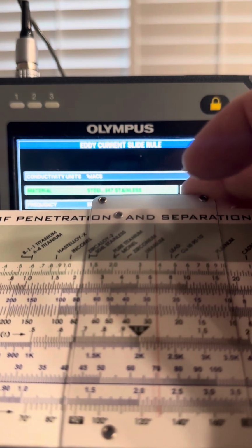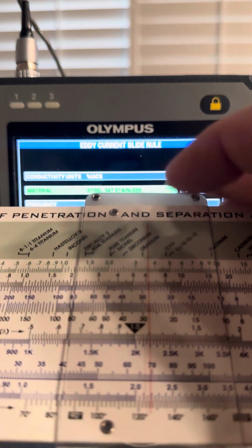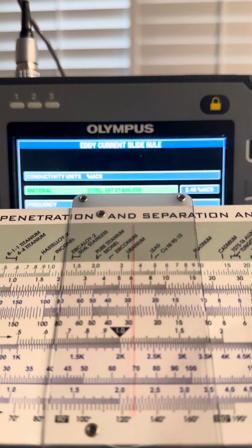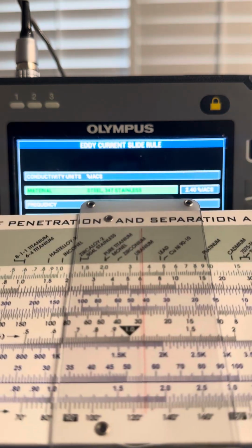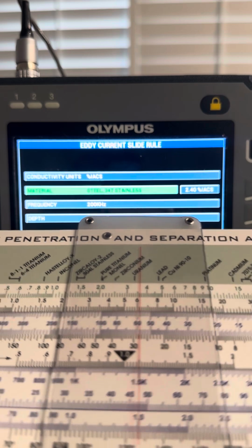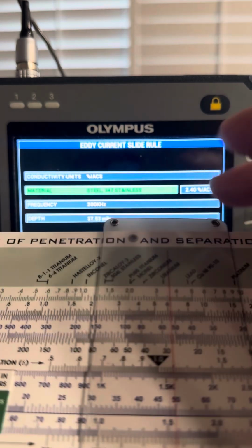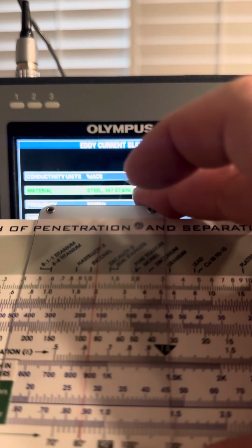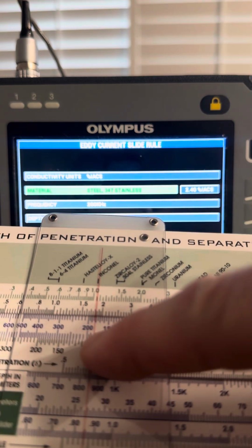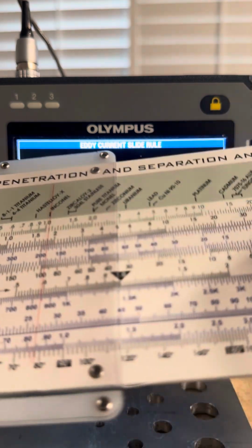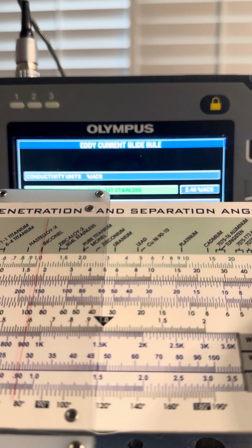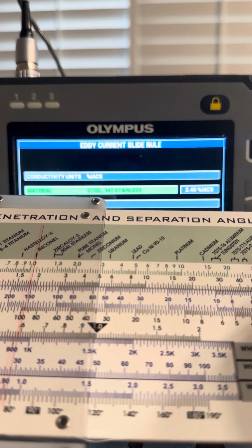Set it to 1.1, and Inconel tubing in steam generators, for example, is close to 50 mils again. So if we put 50 mils at the red hairline, right about there, and then move the slider over to Inconel, our F90 frequency is about 180 kilohertz. Okay, so that's F90 for surface and tubing.